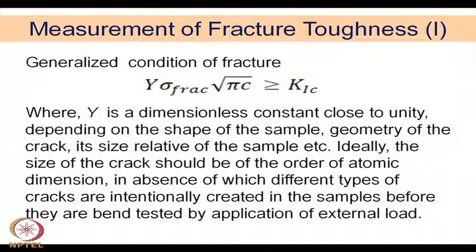Which is always not true, sometimes there will be larger cracks also. In absence of which, different types of cracks are intentionally created in the samples before they are bend tested by application of external load. As you have seen earlier, we have made our calculation assuming that the curvature of the crack tip is of the order of the atomic dimension. However, a crack of the atomic dimension is almost impossible to be created.